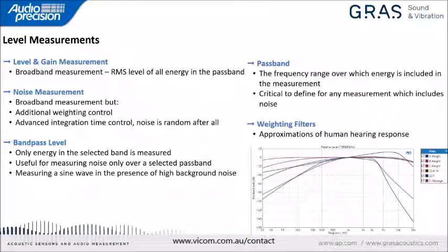But the noise was attenuated with an A weighting curve, which attenuates low frequency sounds and very high frequency sounds, and actually has a little gain in the mid-band because our hearing is actually sort of tuned for the center of sound in human speech. And that's an approximation, a way to provide a score, if you will, for noise that approximates how humans would perceive that loudness.